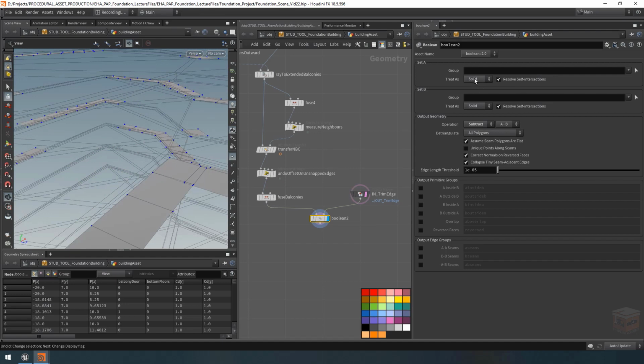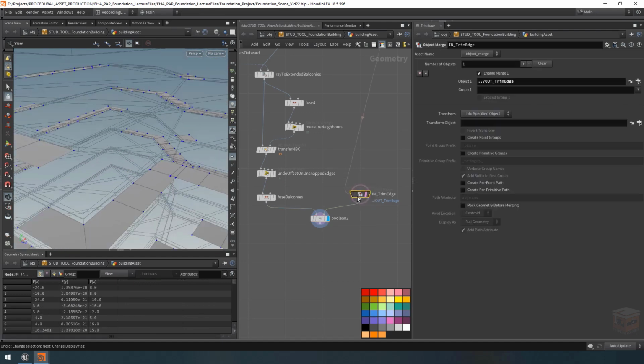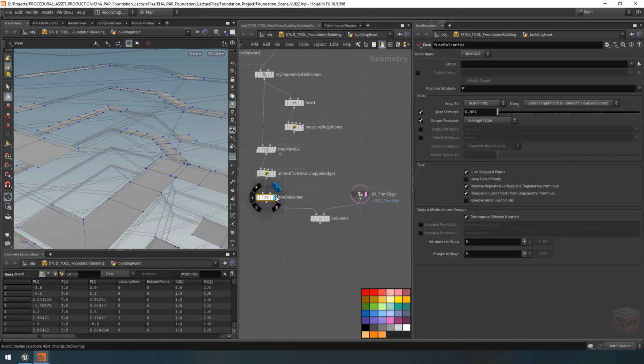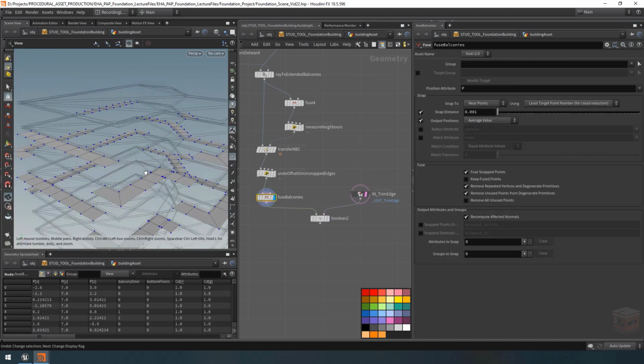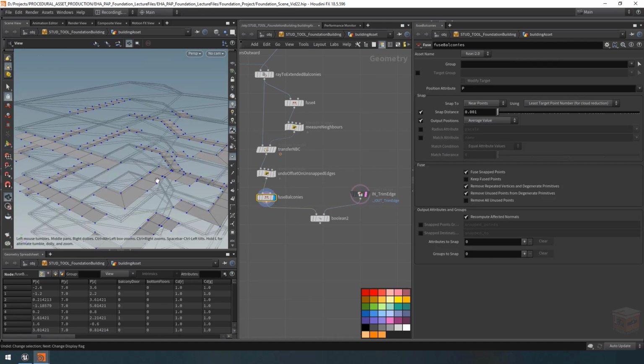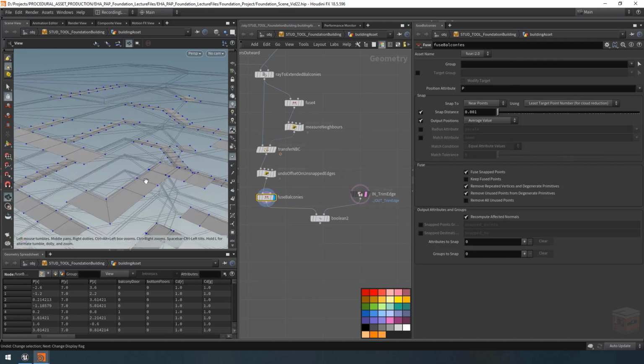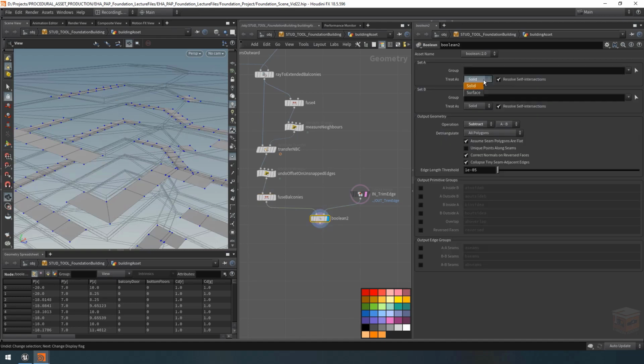We are currently evaluating the mesh here as a solid, but we are also evaluating this mesh as a solid as well. And this is not a solid, this is actually a surface. It doesn't have any depth. So just in case, I'm going to set this Boolean node over into treat as surface. Now that will work again.